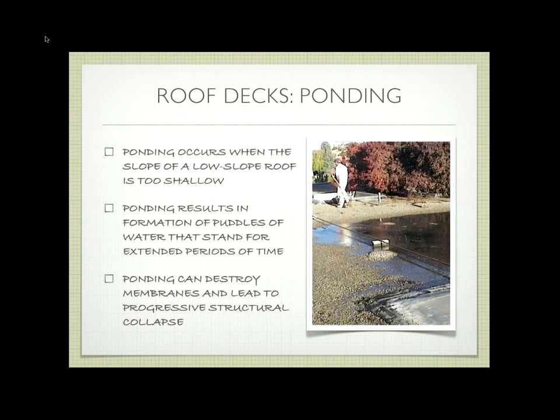When the rain happens and it ponds, it slowly deteriorates that particular area because it keeps a pool in that area, deteriorates the roof. So if you look up there, you see that's where it all drains through. Okay? So that ponding has an effect that will eventually deteriorate whatever the roof membrane is itself, which causes leaks and ultimately failure of the roof.